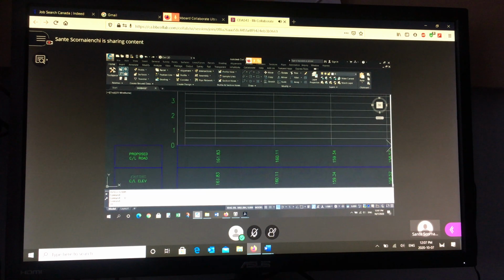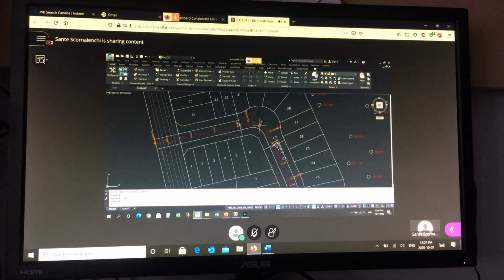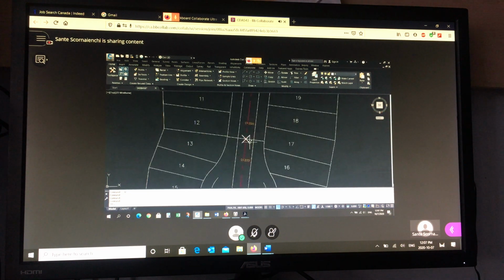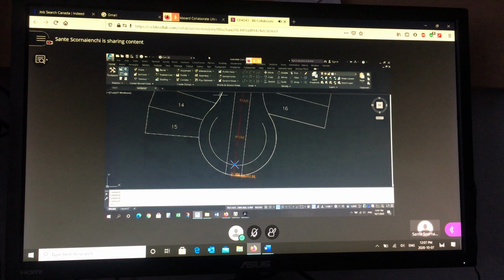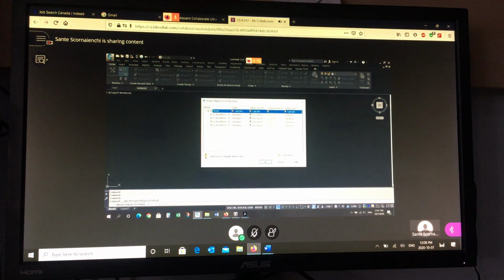Let's do this again. Same function, and do something a little smarter. So I'm going to go back to here. Choose the points. These are the points I want to project to my profile. I'm going to start the project objects to profile view. I'm going to pick the grid. And instead of accepting those zeros, I'm going to go to elevation options, select all, and temporarily say, you know what, get your elevations from the existing ground.